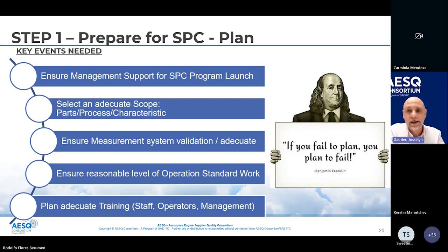And after that, really important is to explain to the key people in this process, who are the operators. As you know, in manual SPC, the operator will be the one who takes the measurement, who will report the value on the chart and raise a hand when something is not going as it should. So we need to train them. We will see afterward what we need to do for that. Next, please.